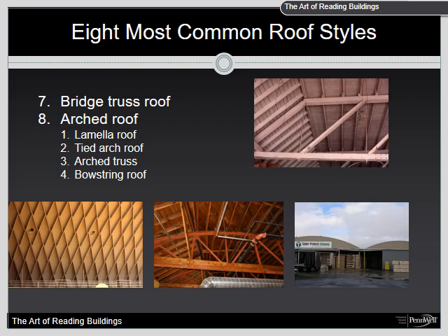Arched roofs. Oversimplified, the fire service text categorizes all arched roofs as bowstring truss roofs. The bowstring, however, is one of many methods used to achieve an arched roof shape. An argument exists that firefighters should treat all arched roofs as bowstrings due to the well-documented history of catastrophic collapse involving them. We get that. We can also argue that the tied arch is more dangerous than a timber bowstring. The four arched roof construction methods covered here have unique characteristics that could influence the firefighter operation.